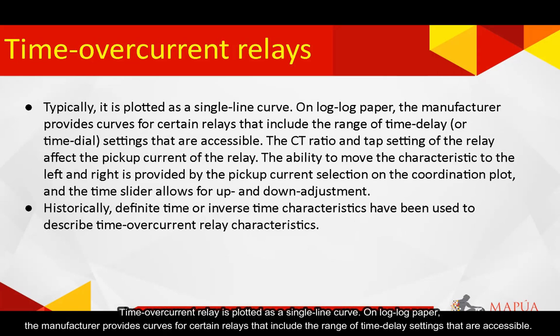Time overcurrent relays are plotted as a single line curve. On log paper, the manufacturer provides curves for certain relays that include the time range of time delay settings that are accessible.